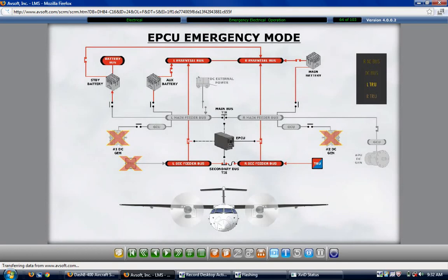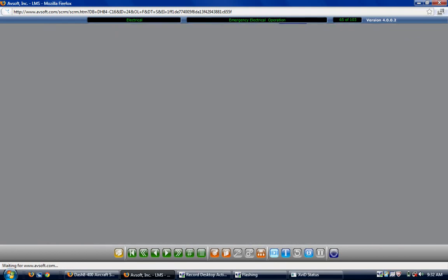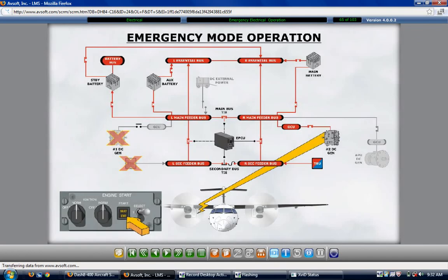During the emergency mode, the main and auxiliary batteries are automatically reconnected to the main buses should you attempt an airborne engine start. The connection of the batteries to the buses occurs even if the respective individual main battery, auxiliary battery, and standby battery switches are in the off positions. Remember, the main and auxiliary batteries are used to assist in engine starts and have a two-way flow to and from their main buses. The standby battery has only a one-way flow for recharging. The battery's connection to the main buses is only for the duration of the start attempt.